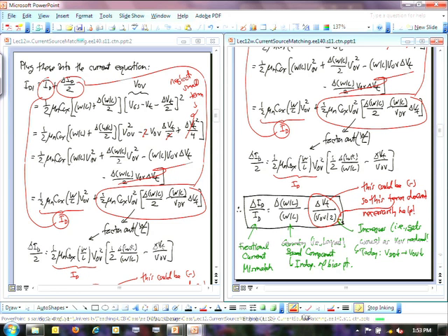So for this to occur, you have to eliminate voltage division that occurs at the input and output when you have a source resistance and a load resistance. And so this happens when your input resistance is infinite for your op amp and when your output resistance is 0. Okay, so what do I mean by that? So if I had to draw that out, say this is my amplifier with a gain A sub V.